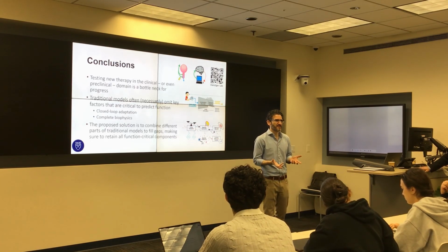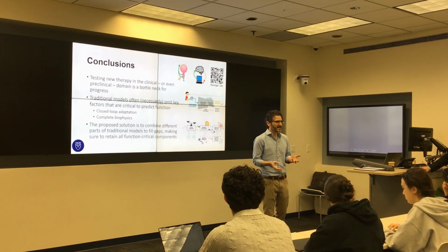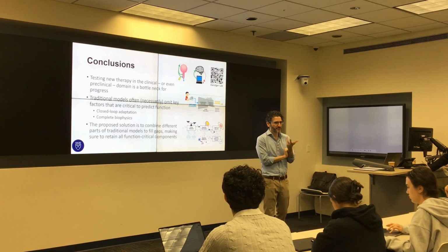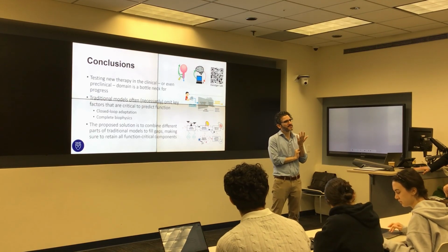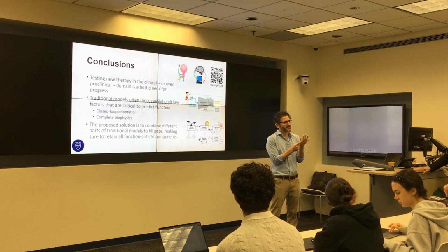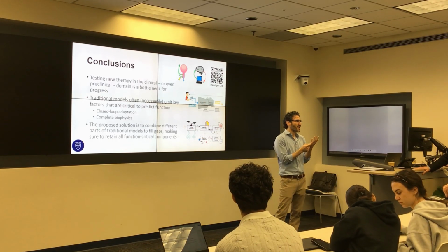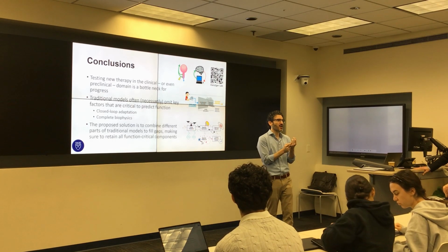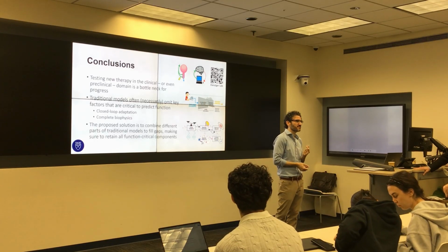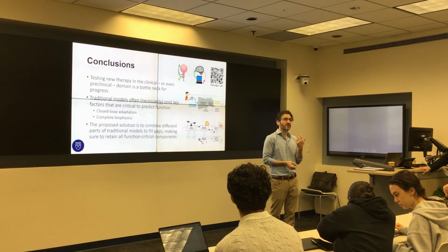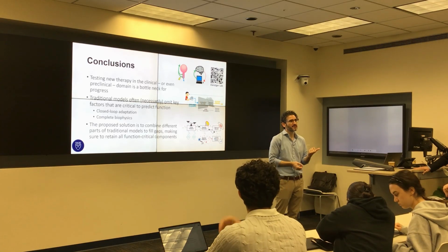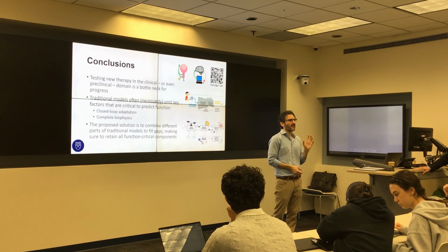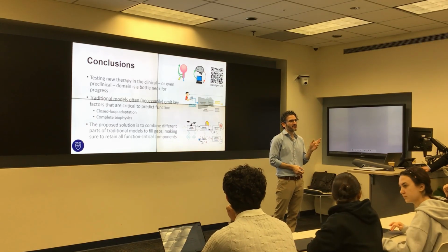Imagine a kind of spandex glove, and you stretch it over your hand so it fits very snugly. Across all of the joints in your hand are stitched something called piezo-resistive sensors. Basically, as you stretch them, they emit different amounts of current flowing through the circuitry. So what we literally measure is how much those sensors are stretching over each joint, which is a proxy for the shape of your finger joint angles.